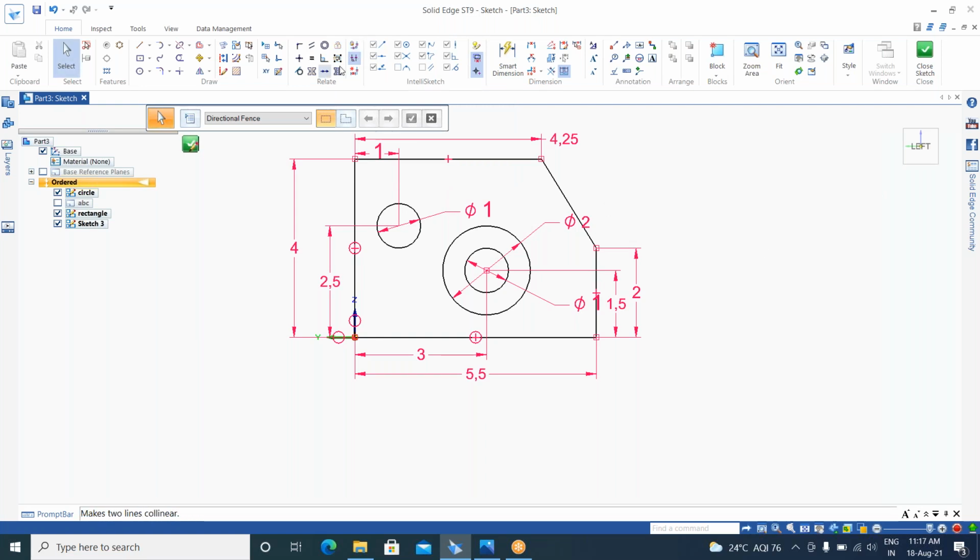See, only relation handles are there, and I will tell what relation handles are. We can clearly see all the relation handles here. Like connectivity, concentricity, and collinear, every relation has those handles, and those handles are visible. If we turn it off, every relation will be hidden. See, every corner's relation handles are hidden.